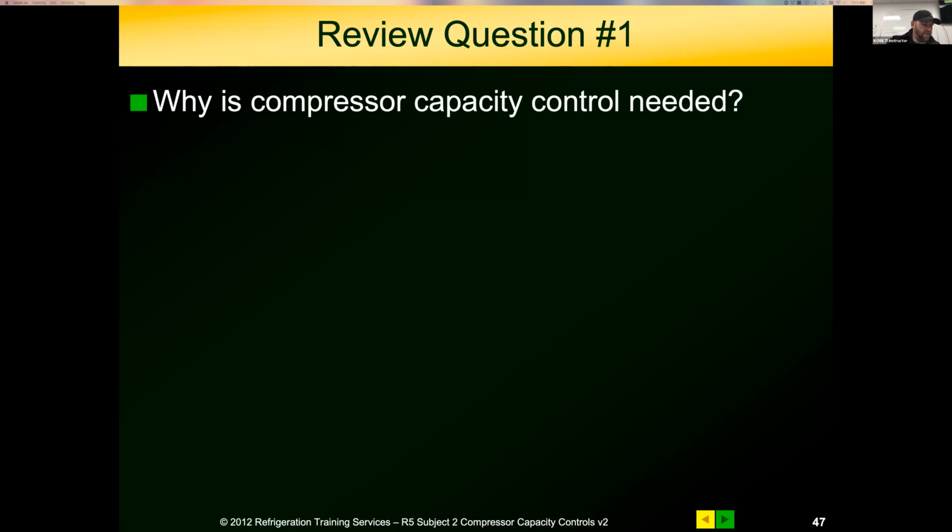When you're dealing in Costcos and stuff, oil can be your worst enemy. If you start getting breakdown conditions on any one of those 13 compressors tied to that rack, you're going to have a bad day. So we want to be doing those check downs, making sure we're getting good cooling to those compressors, good cooling to that oil.